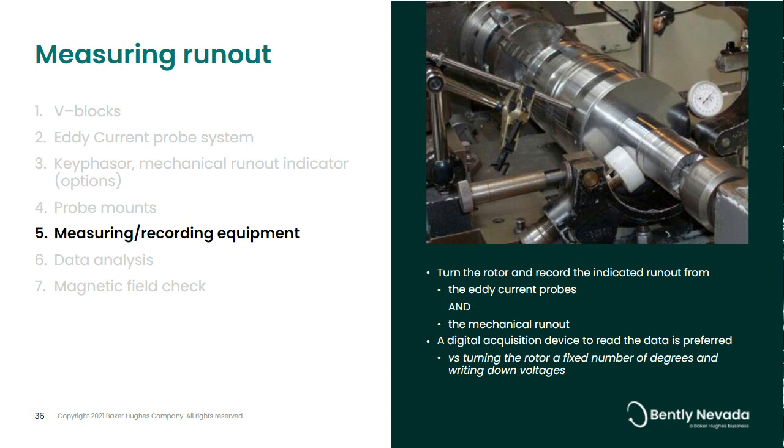Bentley Nevada, you could use an Adre, for example. This will be able to, if you get the right instrumentation, bring the information in and record that constantly as that shaft is rotated at a constant speed. This gives you a very clear, very fine resolution picture of what the surface of the shaft looks like. However, we recognize that that's not always the case.